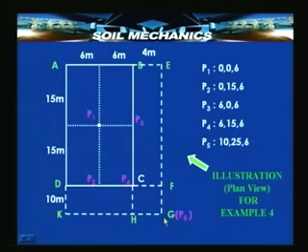As far as point G is concerned, we need to do this in 2 stages. For example, AEGK can be considered to be one rectangle where G is below one of its corners. However, the given loaded area is only ABCD. So, if we take a larger area AEGK, we will be overestimating the stresses at the point G.